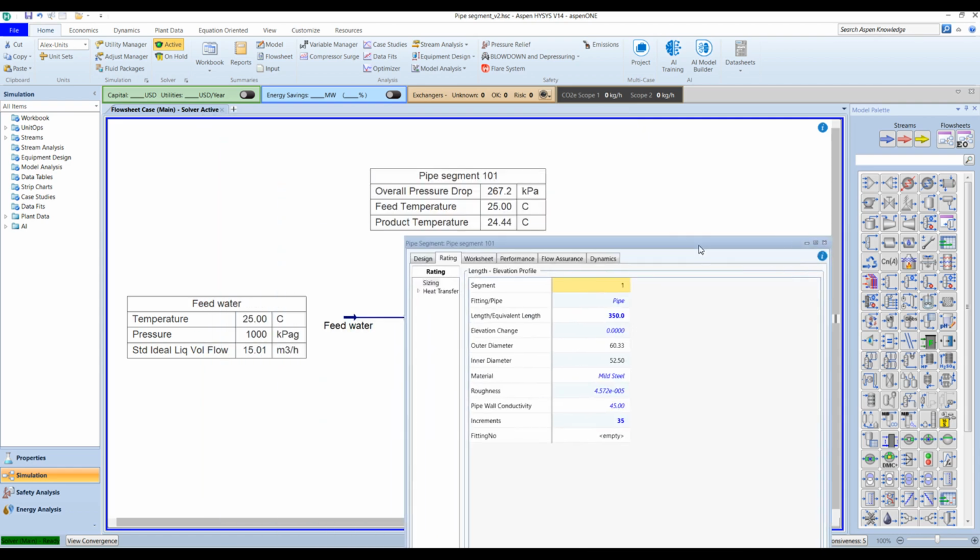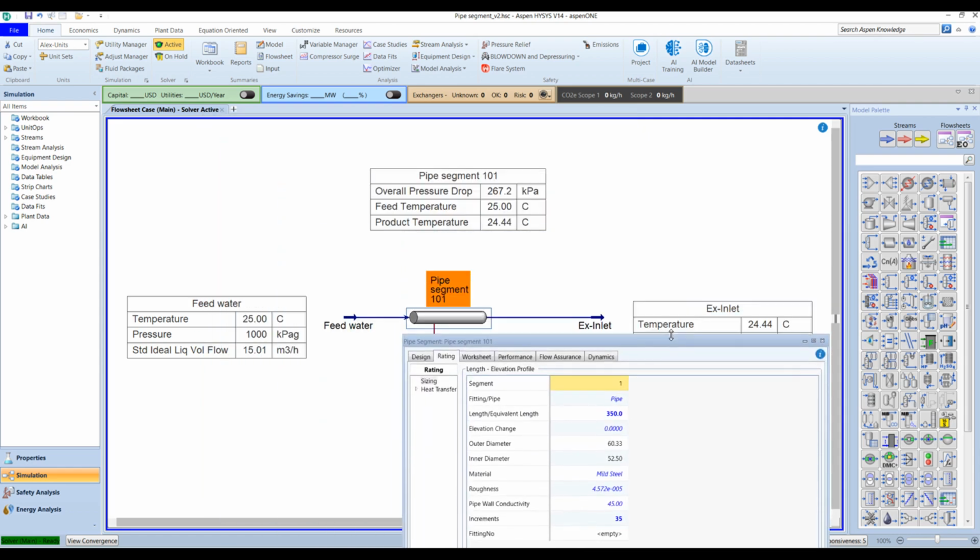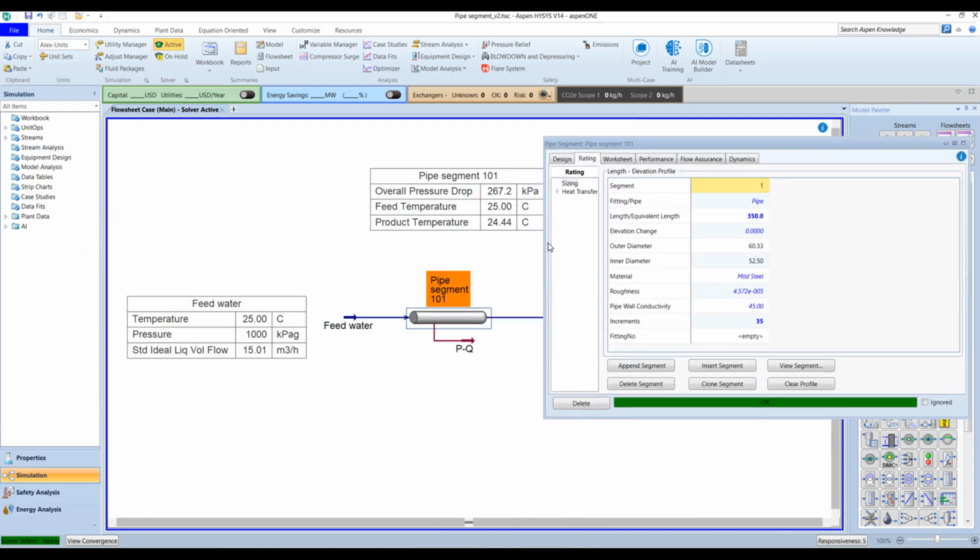If you remember, we've put in this piping geometry from our first video. If you remember from the sketch, we had the tank, and from the tank, the first section of the line was 1 meter of pipe. So I'm going to change the length of this pipe to 1 meter to represent that section of pipe. And then for the increments, I'm just going to use 2 increments, breaking that 1 meter section of pipe into 2 segments, right?